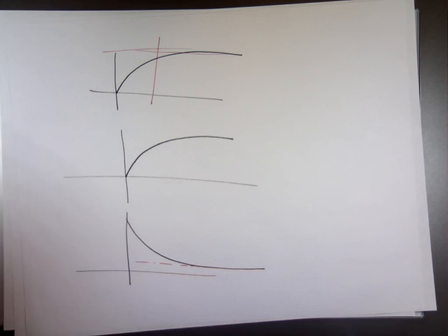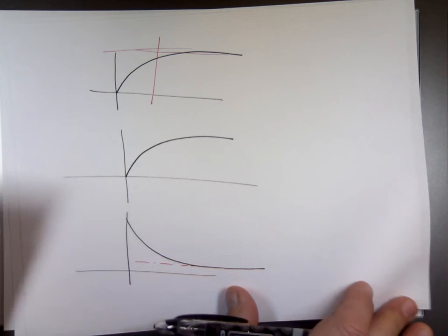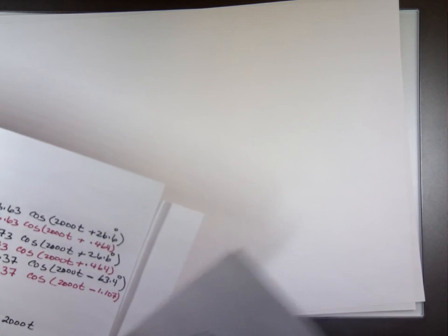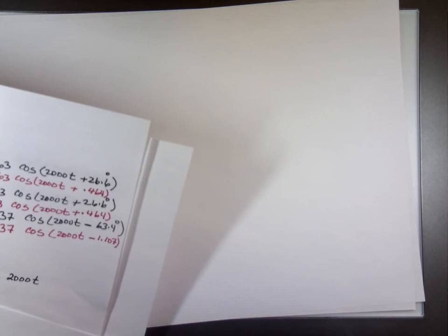It's obvious that a source will supply power, but I keep getting a positive number for the calculation for the source. Do you just throw in a negative? No, if you put the values in, actually, you have to add that minus sign here because you're entering the negative.